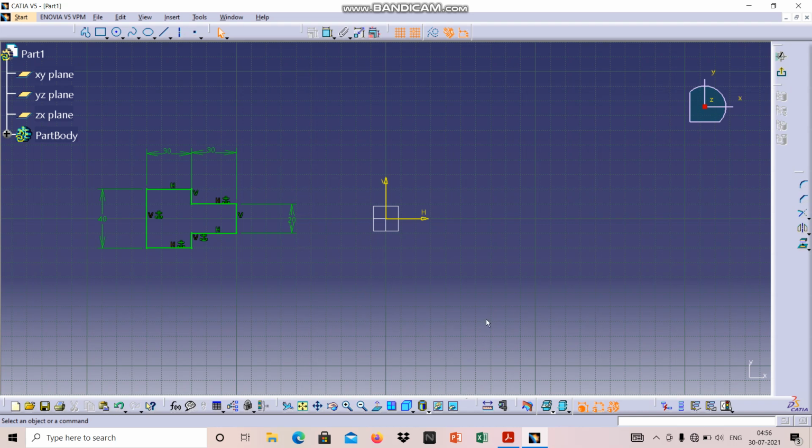Okay, I'll show you one more way in which the same sketch can be made. Again, we need to know all the aspects of CAD here so that you can draw it in a much easier way, and you can use different tools for that. There are many ways of doing things, right? So again, I'll draw this by using a mirror command now. For the mirror command, I need a line first, or an axis about which the command is to be used. So let's create an axis first. I have to use this to create an axis. So this is the axis.